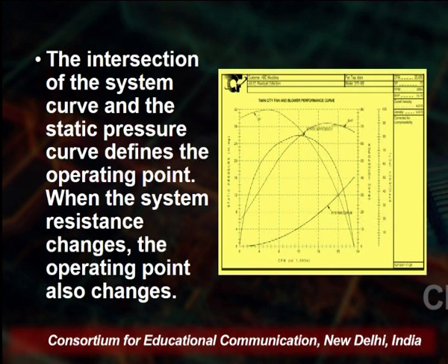On the screen we have the characteristics curve of the fan. The intersection of the system curve and the static pressure curve defines the operating point.